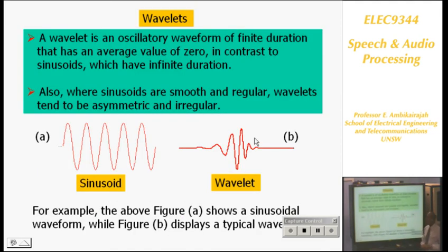So if you look at the wavelets, for a short time Fourier transform, this is the basis function we use, a sinusoid. For a wavelet transform, this is the basis function. This basis function, from there to there, is the window size. And this can be modified, compressed and stretched. Whereas here, you don't compress or stretch, you use a fixed waveform, whereas here, you change them around.